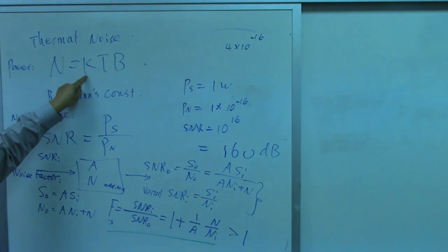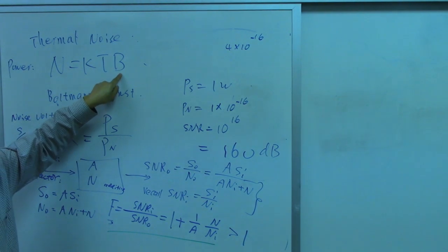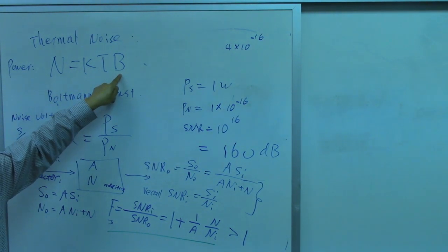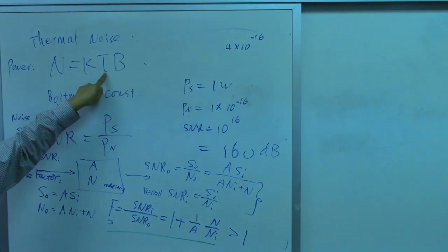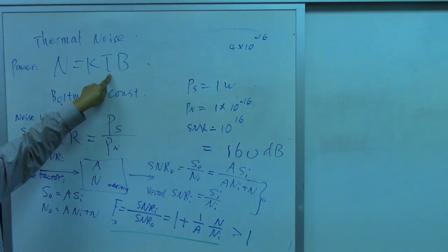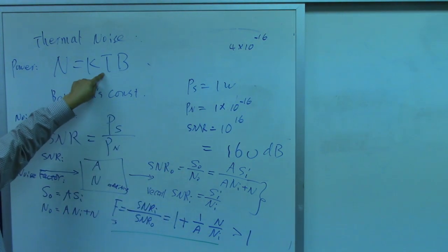Thermal noise is k, a constant, times T times B. You make B equal to 0, that means no bandwidth. Then why do you want that system? No bandwidth, we can do nothing. So the only thing we can do is make T equal to 0. How to make T equal to 0? You reduce the temperature of this thing, up to absolute 0, and put this in liquid nitrogen or even lower, outer space. Right? At least make this one as small as possible.